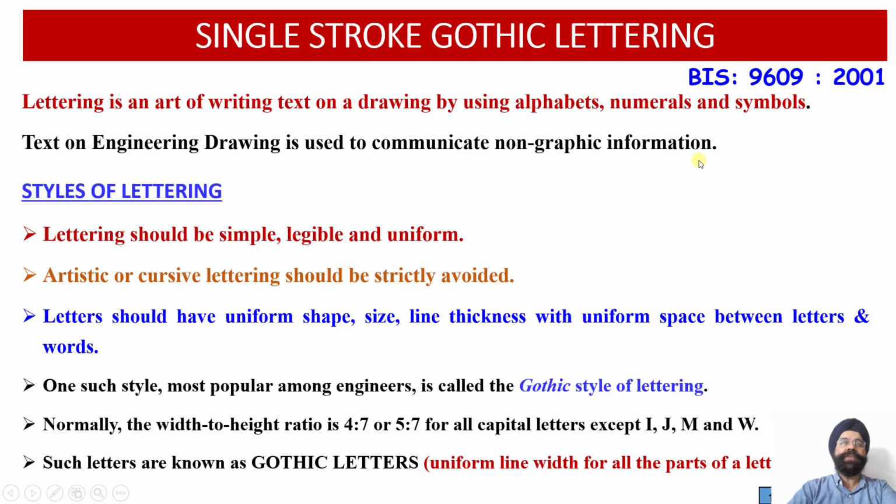Now you see, we have seen that whenever we are talking about normal lettering other than engineering drawing, we put down cursive lettering, we have artistic lettering. But so far as engineering drawings are concerned, we have to avoid all those things. So far as putting down the text onto the engineering drawing is concerned, the lettering should be kept simple, legible and uniform. This is the primary requirement.